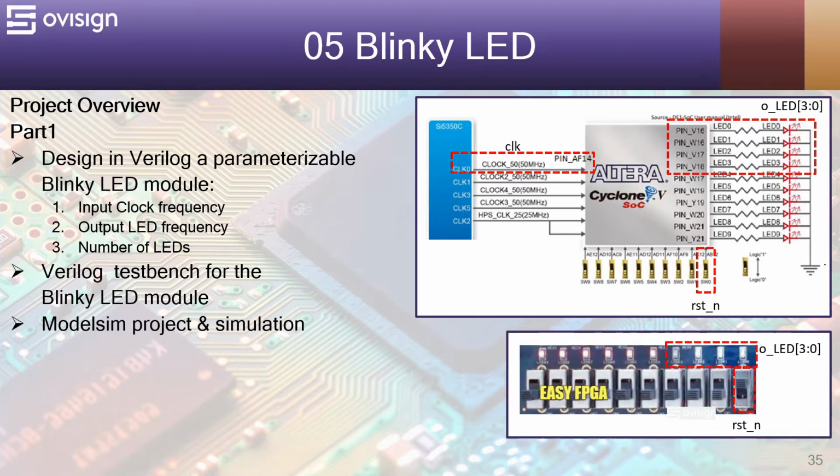You are going to be able to change the input clock frequency, the output LED frequency, and the number of LEDs. Next, we are going to create a Verilog test bench for the Blinky LED module. In the end, we are going to create a Modelsim project and perform a simulation.